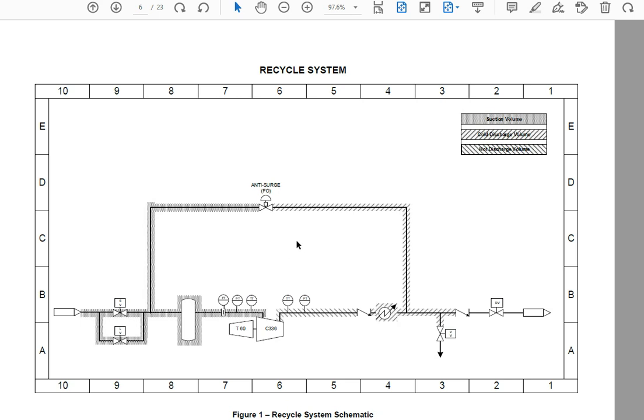Many years, many compressors designed with this arrangement, and most of them surge on fast stops. How big a deal is that? Usually not a big deal. You'll see some vibration, maybe some seal wear, but usually not a terrible thing.